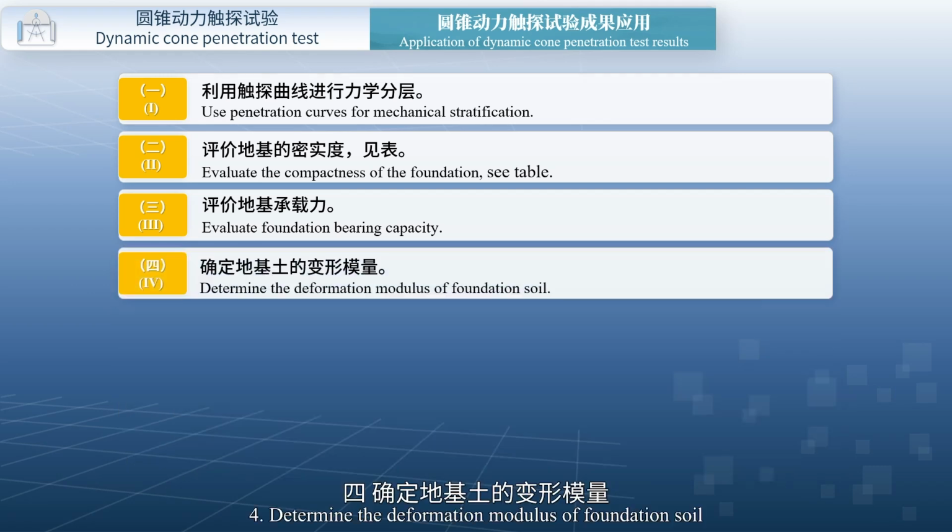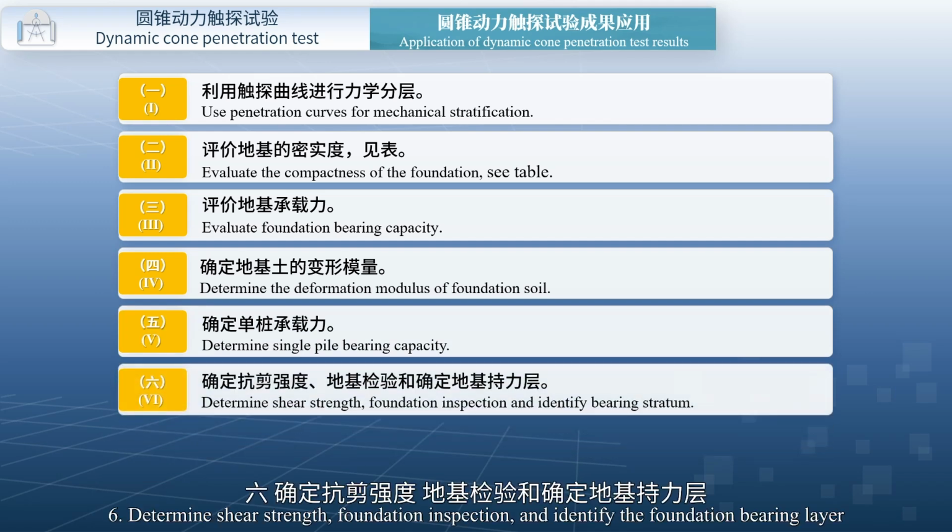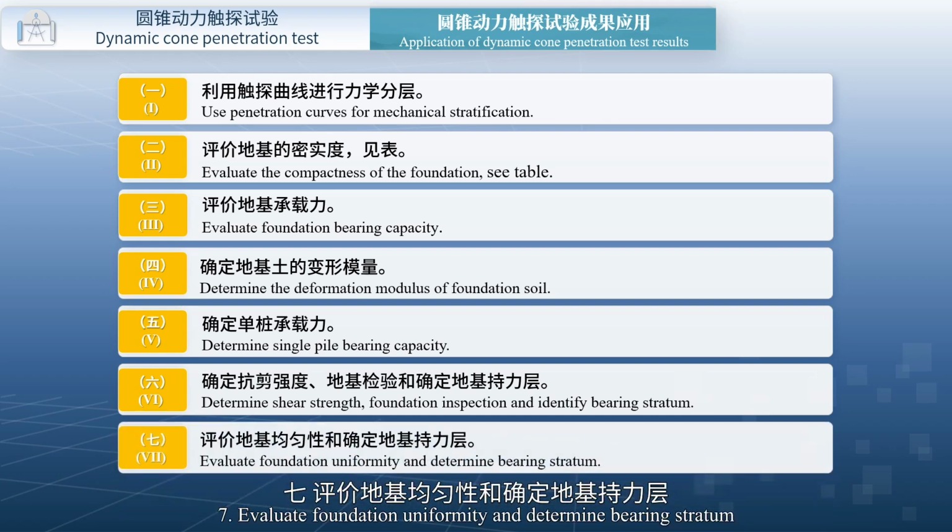Fourth, determine the deformation modulus of foundation soil. Fifth, determine single pile bearing capacity. Sixth, determine shear strength, foundation inspection, and identify the foundation bearing layer. Seventh, evaluate foundation uniformity and determine bearing stratum.